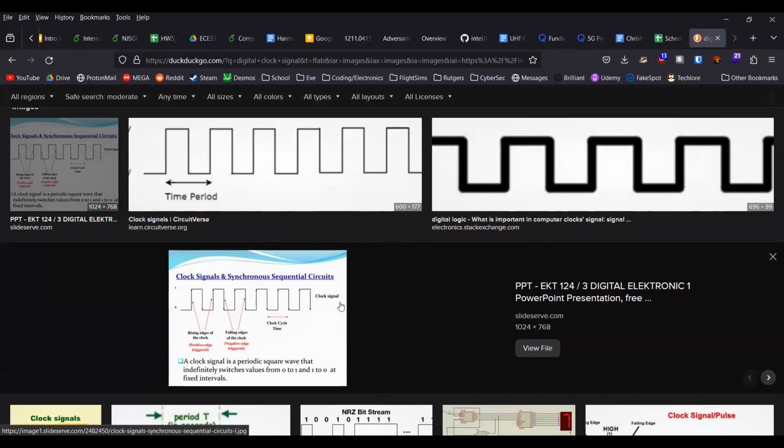So a clock is typically a signal. In this case, it's normally a digital square wave going up and down. Think of it like a drum for electrons. It's just repeatedly switching up and down, and that creates your timing. Because it's a wave, the gap between here and here, that's the period. So then that period can be used to sync up the devices.